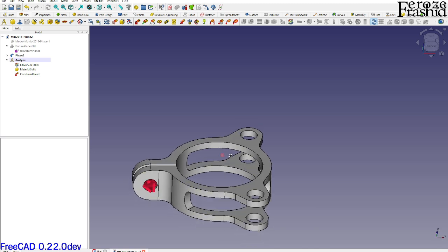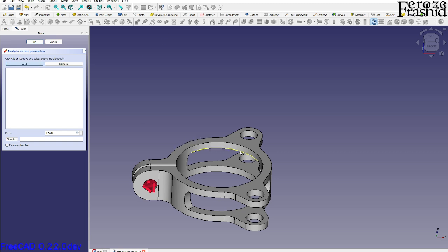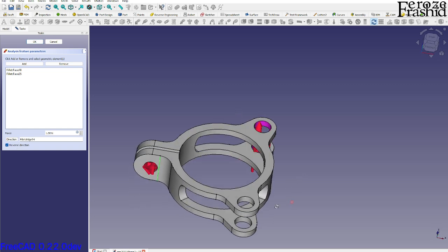Okay, now loading part. I want to go ahead and apply. So add this. I want to pick. Okay, so I probably want to pick this one as well. And then take this add option off by clicking on it, and then select this line, which is going downward or upward, and then hit direction. So that brings it downwards. If we wanted to have this load applied upwards, we would just say reverse direction. It will come upward, but downward is fine with me.